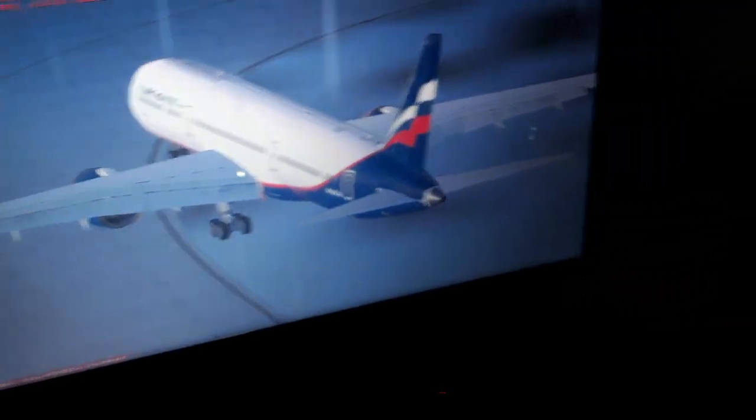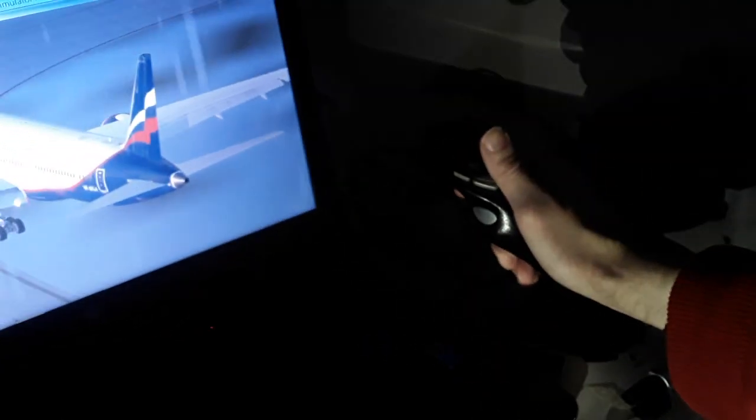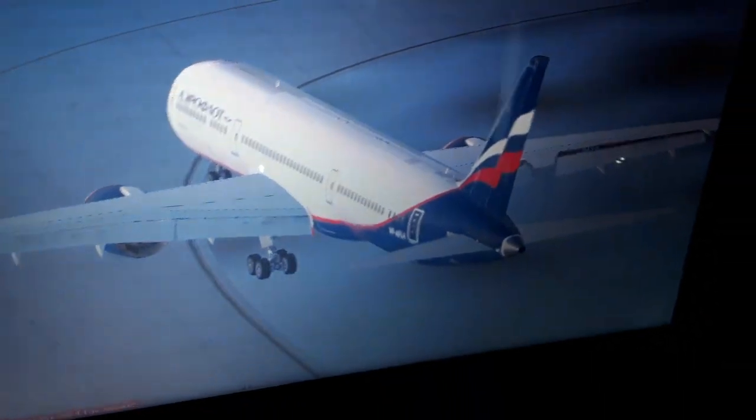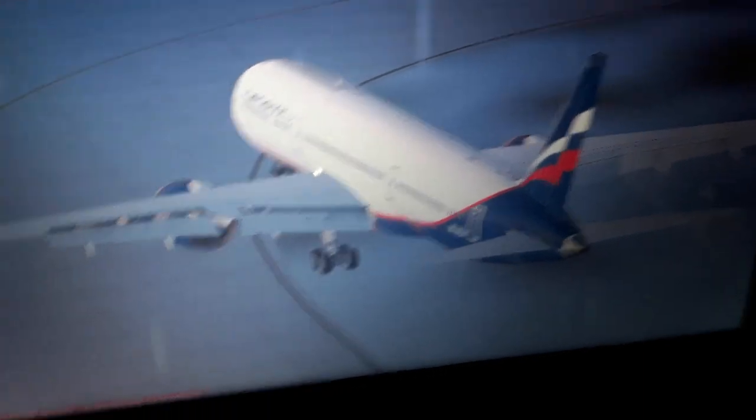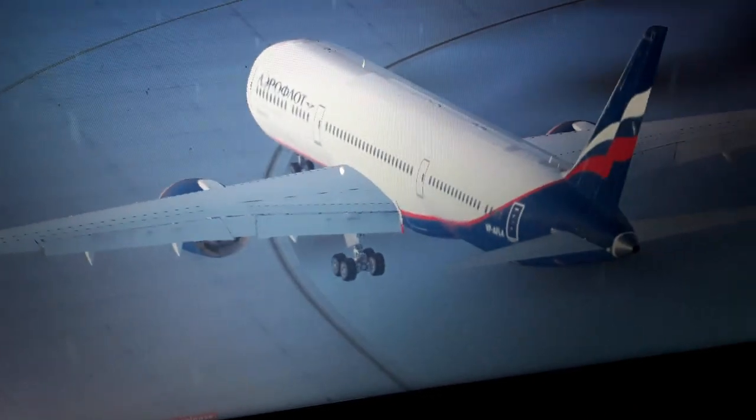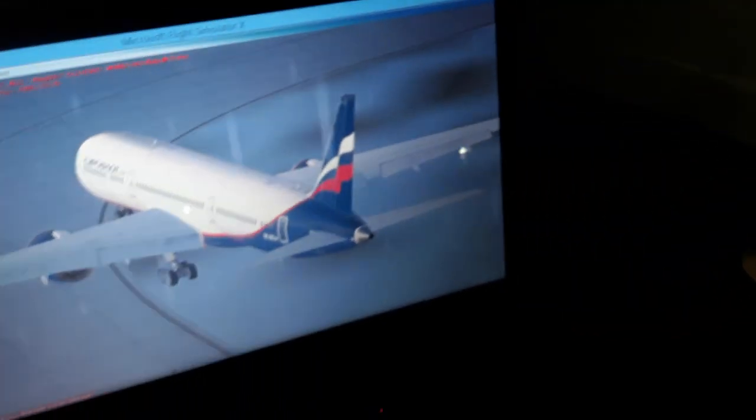As you can see, left and right turns, side stick left and right in the Airbus. Also the control wheel left and right in the Boeing. In the Boeing you also have aileron, spoilers and the flap surfaces to control the turn left and right.